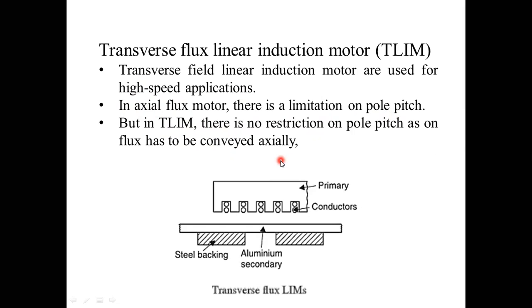If you observe normal motors also, the pole pitch has to be designed differently because of the advantage of getting the flux value or the field strength within the air gap. So the transverse linear induction motors have no restrictions on pole pitch, as no flux has to be conveyed axially.